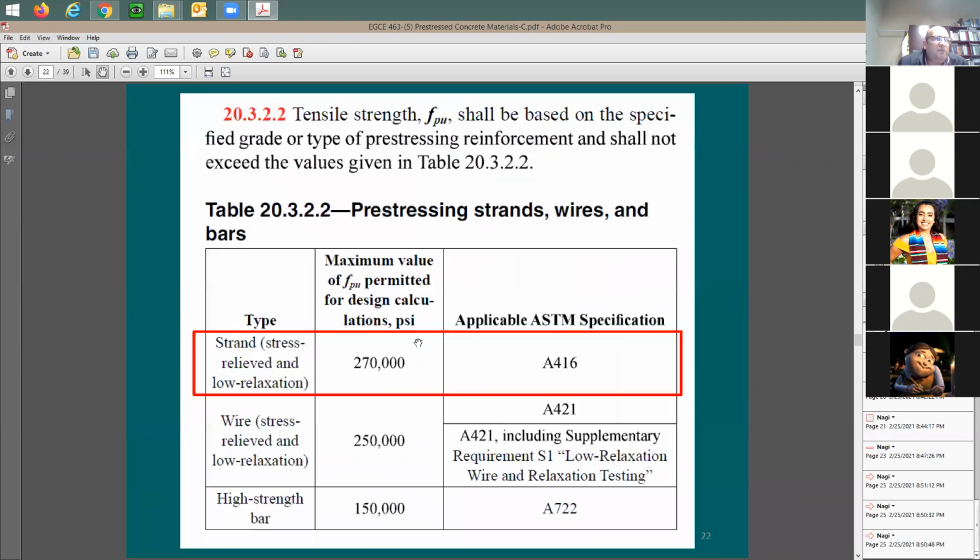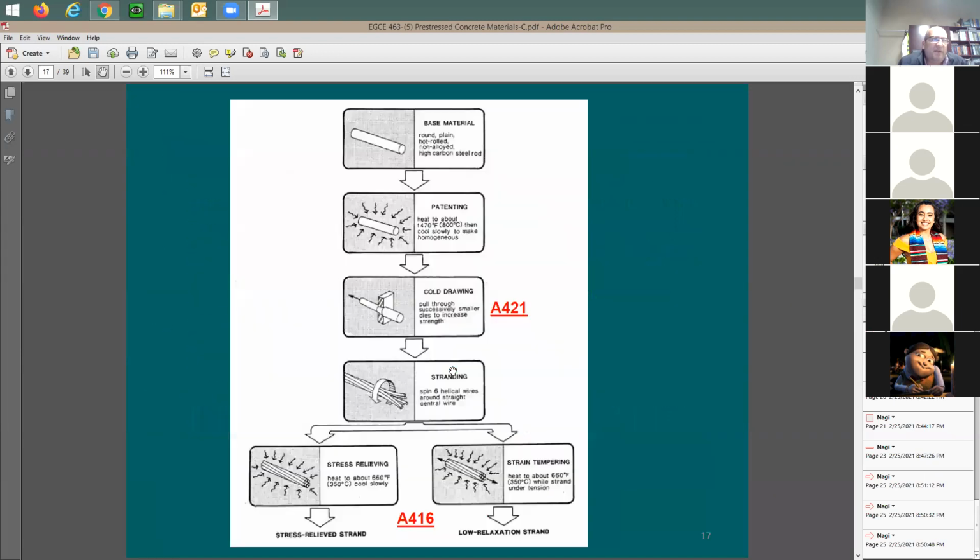So what is the benefit, let me go back to this graph, of putting this tension while you are cooling it down? You heat up the strands and then cool it down. The benefit is less losses. By how much? The losses here are going to be roughly a fraction of the losses there, because it's a factor of 4.5 based on this empirical formula. You're going to have much less losses. Does it make sense? So it allows you to have more stress.